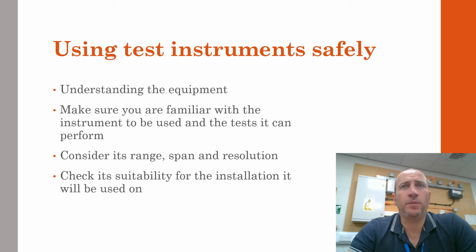It is vital when using test instruments to understand how it works. You must know what you are testing for. Is it the voltage, current, or resistance? You must also know what you expect the result to be in order to select the correct scale.